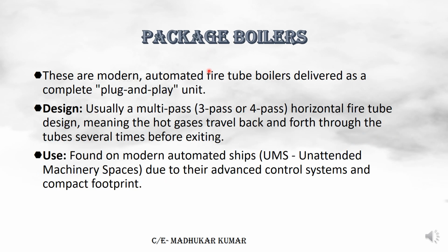Packaged boiler. It is also found on UMS class vessels; you will find packaged boilers like Aalborg and Miura. These are the famous manufacturers for that. So automated fire tube boilers, plug and play unit, multi-pass, 3 pass, 4 pass, basically a horizontal tube structure design. The hot gases travel back and forth through the tubes several times before exiting. Basically, the maximum heat extraction will take place over here.